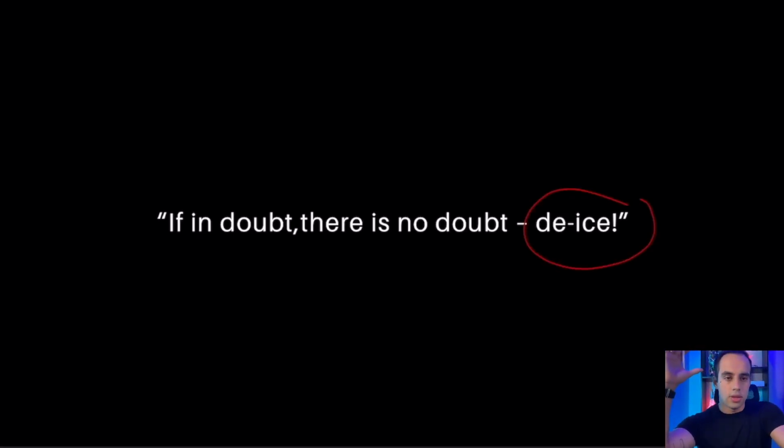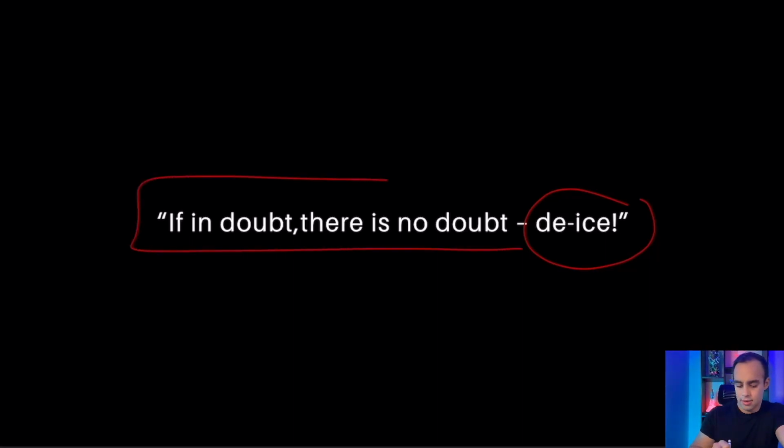But one thing he told me, I think I told some of you today, is: if in doubt, there's no doubt, which is obvious, right? If you're in doubt that you can fly safely, there's no doubt you're going to cancel the flight. If you are in doubt that the weather will be fine when you return, there's no doubt you're not going. If you're in doubt if you're going to have ice accumulation or not, there's no doubt you're going to de-ice the aircraft. Okay, so this is something very powerful. And if we live by these words, things are going to be good for us as pilots, you know.